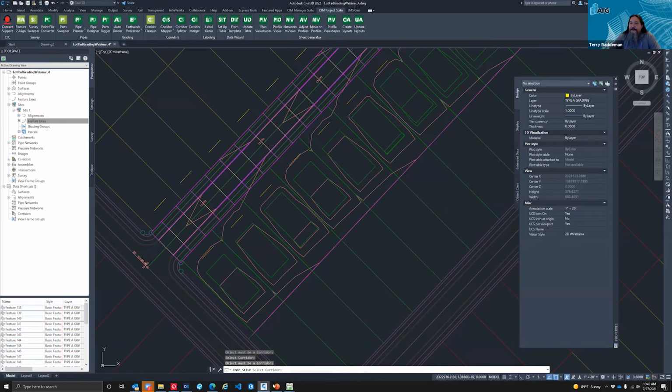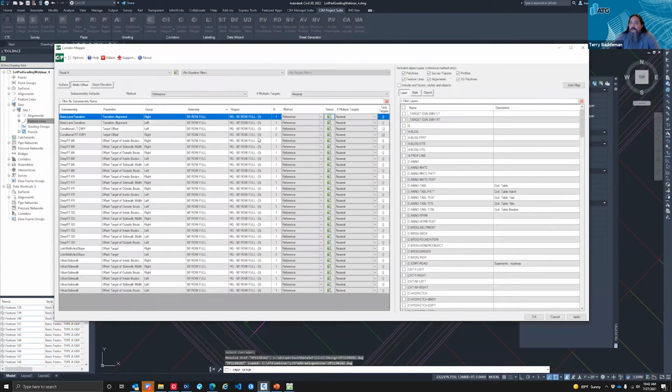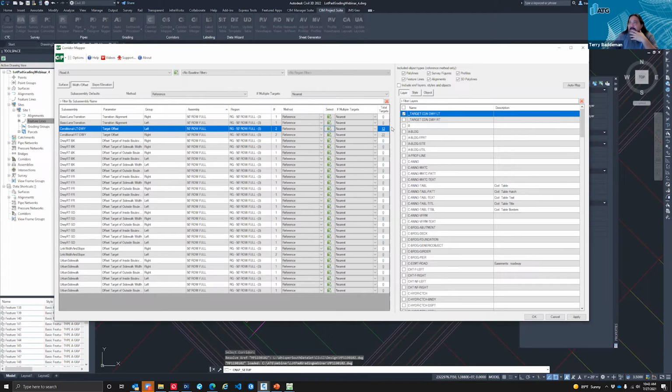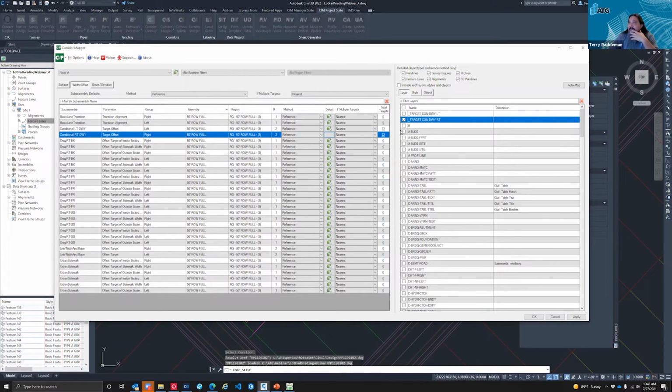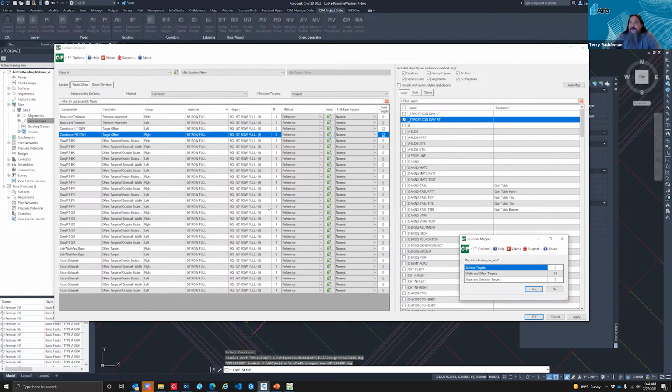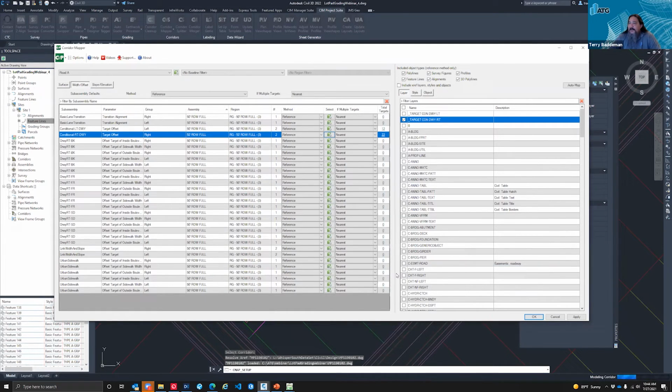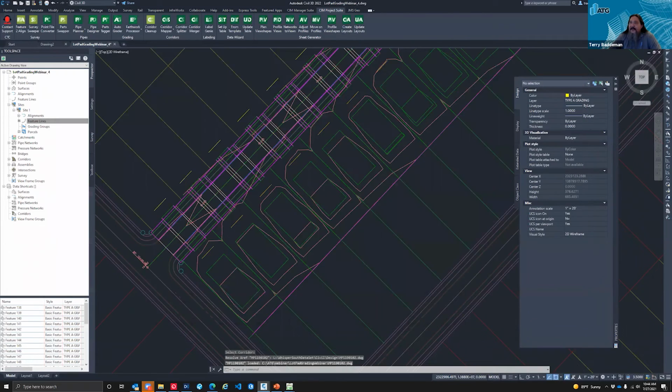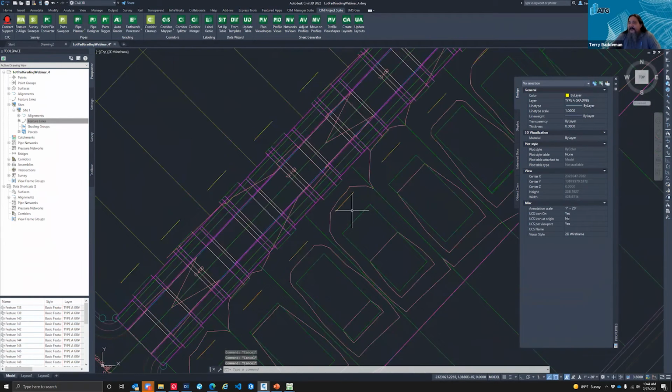I'm selecting. All right. I probably didn't have to redo this, but we have our conditionals. I'm just going to hit OK. Again, we have a driveway left and a driveway right. They're controlled by each of those layers. It found 12 of those, and I'm just going to apply it. I didn't really have to go back to this interface. If I just did the second command there, it would go through and apply our updates. But there we go. There's our driveways, and here's our paths and our lot lines.